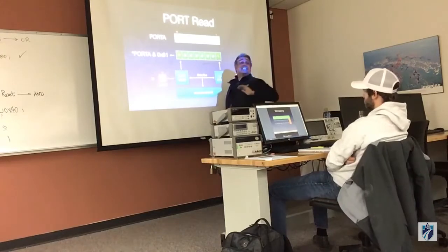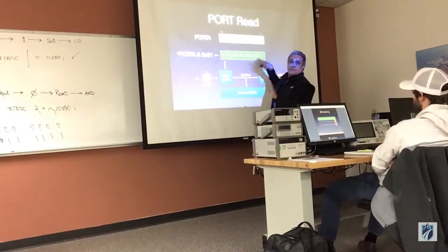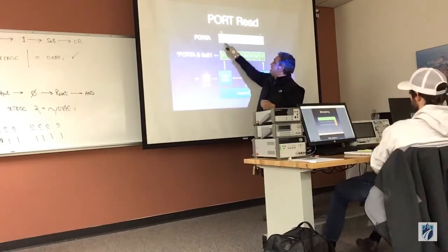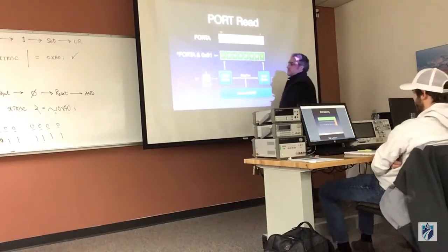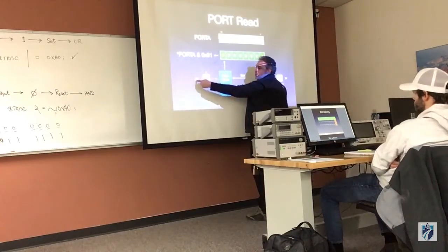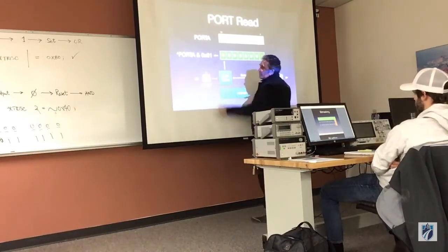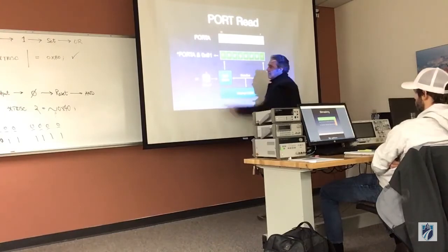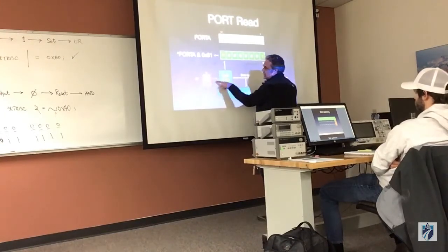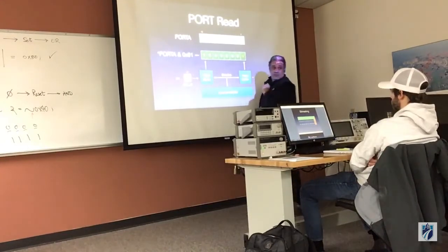That arrow is telling me that before I was capable of doing any of this, somebody set my pin A7 as an input. So that if you physically put a grounded pin on pin A7, I mean I take a piece of wire, I hook it to 13, and I ground that pin. Like you physically ground it. That will put 0 volts on pin 13. The input buffer will pass that data up into port A, the register.